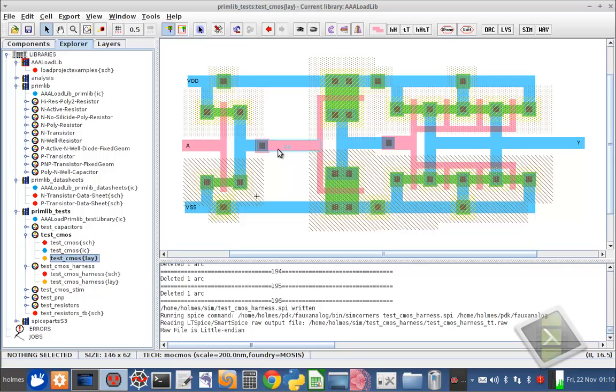So there's a parasitic resistance of this polysilicon line between the output of this gate and the input of this gate. So those parasitics have to be calculated, and also there's capacitance between the polysilicon and the substrate. So all those things add up, and they slow down the device and slow down the functioning of the circuit.